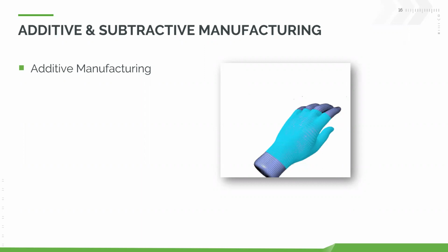You can do a variable wall offset for formula-based lattices. And that's something that in the scope of additive manufacturing is a type of lattice that doesn't require the use of any type of support structure. So that's very useful. And what you can also do now is mix user-defined and materialized style support structures within a given model. Materialized is our metal-based printing processes, so you can now mix that with your user-defined parameters as well.